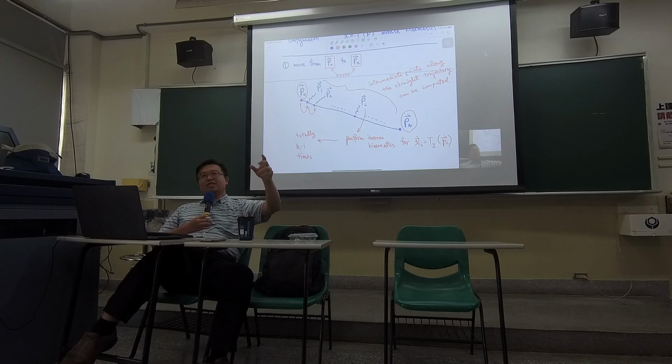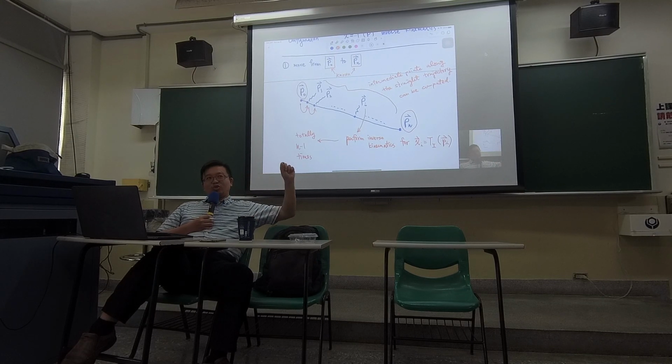In that case, the controller doesn't guarantee that between each point it's going straight. So if you do not use enough intermediate points, it could be moving like a wavy curve. Okay, because you didn't tell the controller what configurations to assign between points.